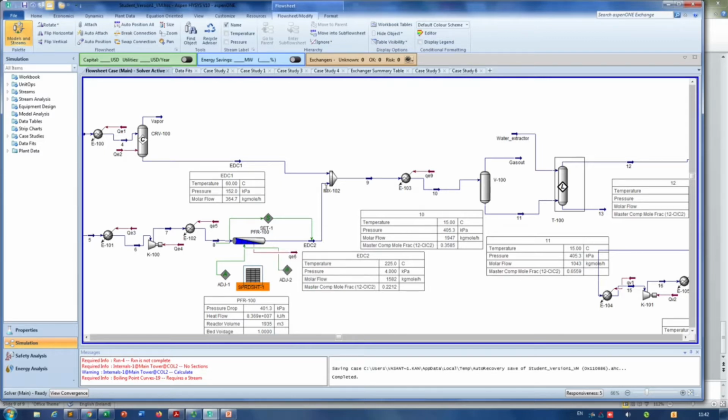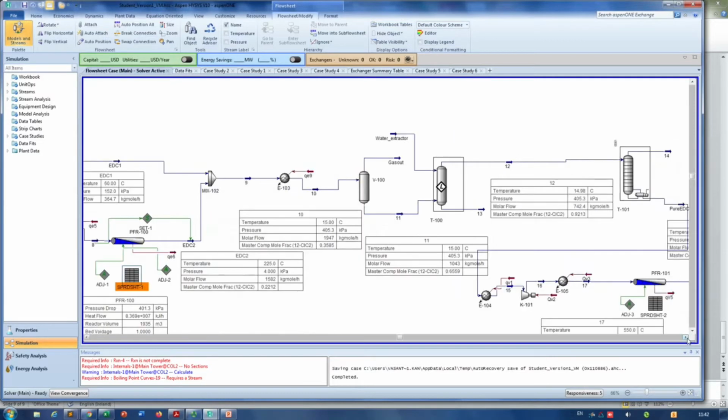And then we take ethylene dichloride from the direct chlorination and from the oxychlorination, and we try to purify that material. Our aim was to get 99.5% pure ethylene dichloride. If you look at the mole fraction of ethylene dichloride, we have 35% purity. So we used a component separator, followed by a 5-stage liquid extractor.